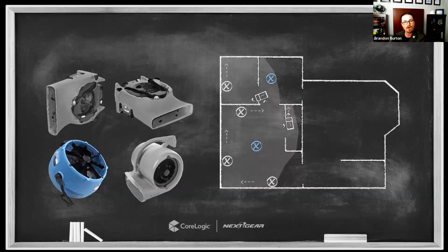All that surface water and all that free water sitting in the pores and openings is just going to continue to absorb. It's going to go deeper into the assembly. It's going to go deeper into the plywood substrate. It's going to go deeper into the slab on grade, whatever it is, it's going to absorb deeper. And that additional 24 hours of absorption is going to add 2 or 3 days to the drying process, because now I've got to dry deeper into those assemblies.